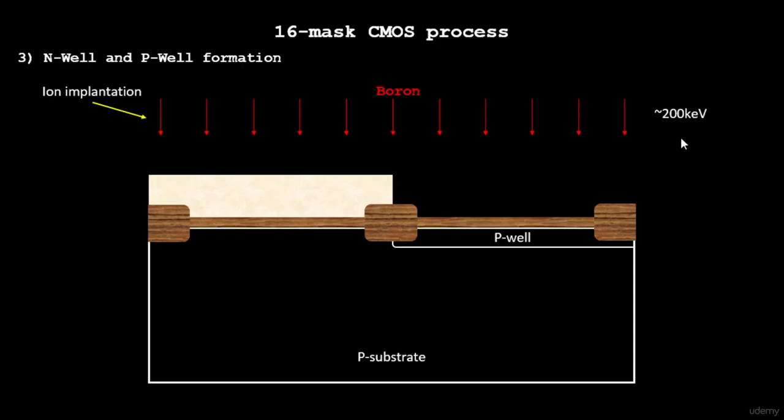Now I will show you how you grow the oxide in the remaining area, and that will eventually act as an isolation layer. But the point over here is that the silicon dioxide area which is under silicon nitride is protected from growing more. Similarly for this area and the other areas, when we put this into a very high temperature furnace, the other areas of the silicon dioxide will grow, while the areas under the silicon nitride are protected. So let's see how it looks. We'll put this complete thing in an oxidation furnace.